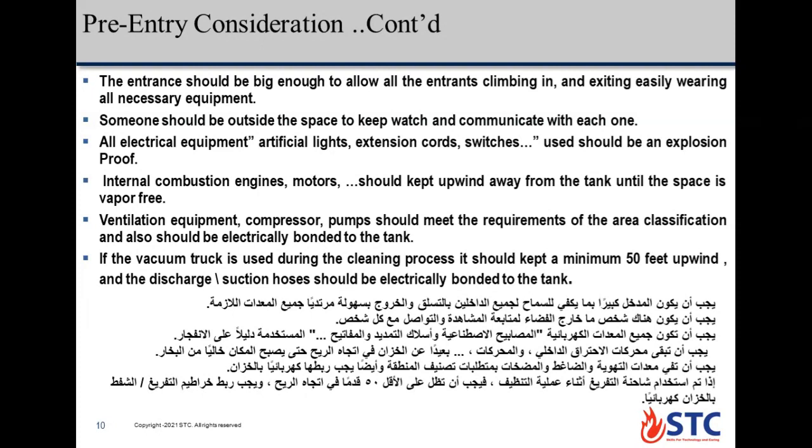Ventilation equipment, compressors and pumps should meet the requirements of the area classification and should also be electrically bonded to the tank.